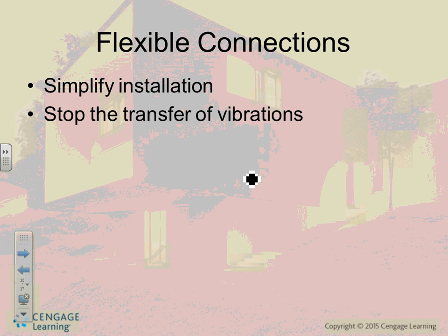This is an equipment run. This is a green conductor, believe it or not. That's qualified. Now, if this is not qualified and that's qualified and you put them together, the system becomes unqualified. So you need to pull what? A conductor. And when you push wires in, this will be the weakest link. It will be hard to push through. Can you do it? Yes. It's a sloppy job, though.